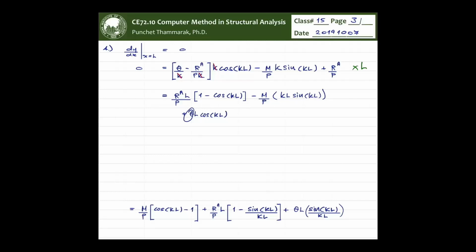We just need to set something to be known. So we open up the angle to a given theta value, so theta will be known. But then what are the corresponding reaction forces and required moment to rotate this beam under the presence of axial force P to this angle, precisely theta? Alright, so theta is known. We need to find out RA and M.